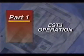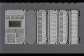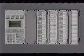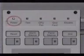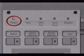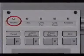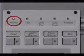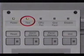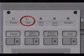Part 1, EST3 operation. Let's begin by looking at the system's primary operator interface, the 3 LCD display, and review its LED indicators and switches. The top portion of the panel contains the system LEDs. The power status LED is a green LED, which is lit when AC power is present. Should this LED go out, it indicates that the AC power has been lost, and the system will switch to its standby power source. The test status LED is a yellow LED, which is lit when any portion of the system is in test mode.